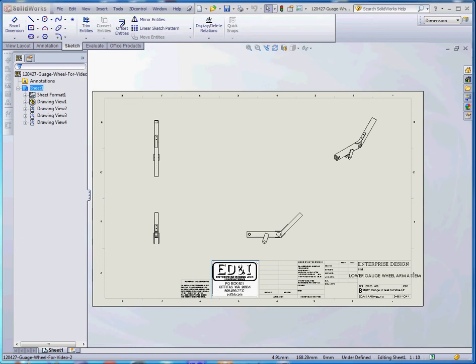It's going to show you how to do a lot of little things in regard to getting our model into the drawing, and of course putting annotations in there like our dimensions and other similar items in order to get a drawing that can be quite literally handed off to somebody so they can fabricate it. And as I mentioned in class, and this is a test question, by the way, you want to make sure that you know that drawings are probably the most widely used way of demonstrating your design intent to other people. It's a way of being able to fully document as best you can the information you want on a part that you want somebody else to fabricate. And that's the purpose of drawings.